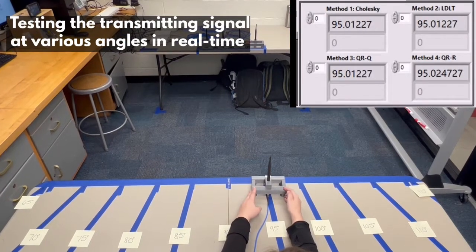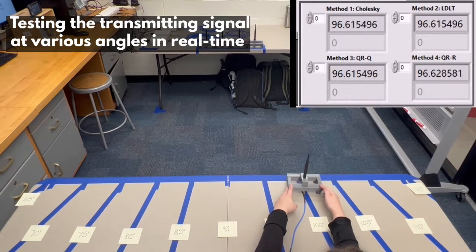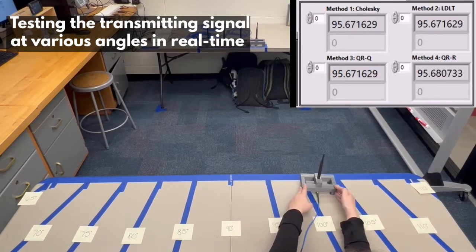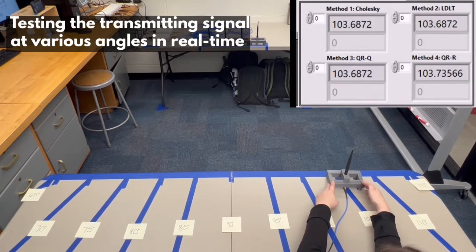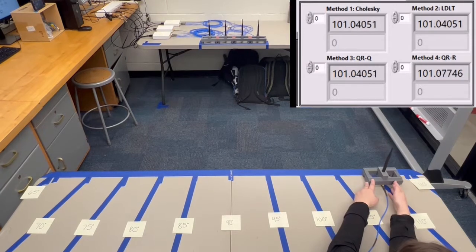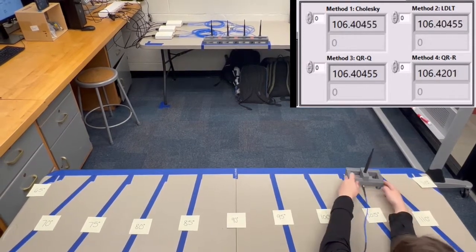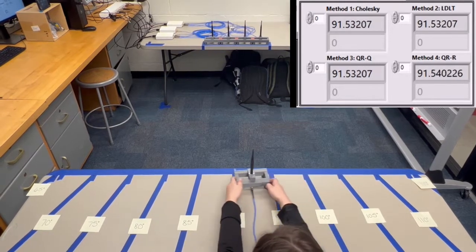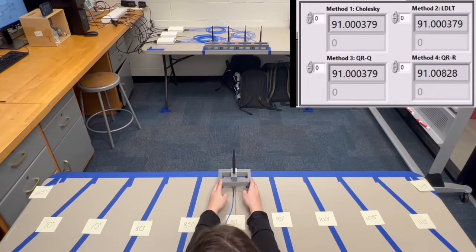In a secondary test, we tried moving the transmitted signal to various angles to see if our algorithm would accurately estimate its location. As you can see, some angles do not accurately estimate as well as others. Due to this, as well as our limited testing environment, we believe that we are dealing with the multipath and reflections of the signal within the room.